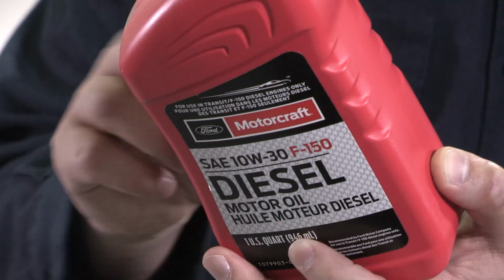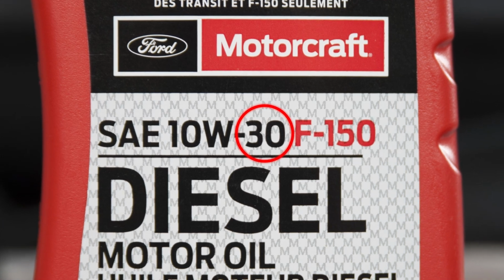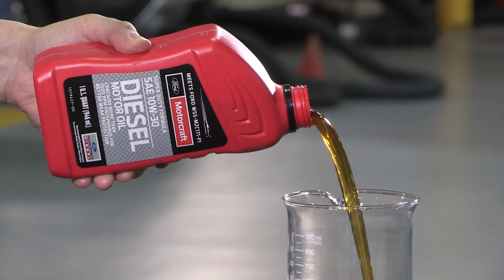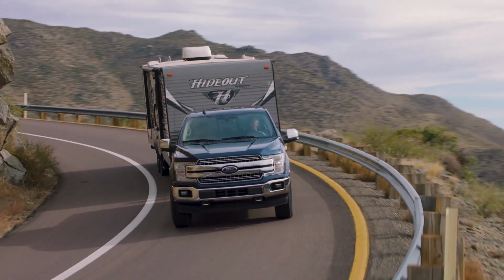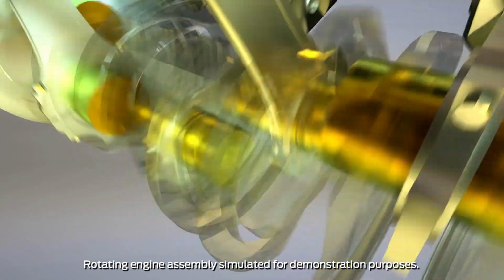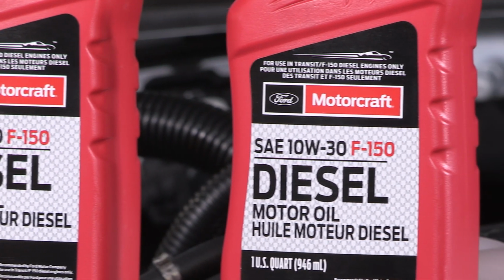There are several parameters that define the SAE viscosity grade, for example 10W30. The 30 consists of kinematic viscosity, which measures the oil's flow under gravity. The kinematic viscosity is the same for new F-150 diesel motor oil as it is for Motorcraft Super Duty diesel motor oil meeting the WSS-M2C171-F1 spec. A second parameter is dynamic viscosity, which measures the oil's flow between two moving surfaces under load. The dynamic viscosity impacts the oil film on moving parts in the engine. The dynamic viscosity is lower in the F-150 diesel motor oil.